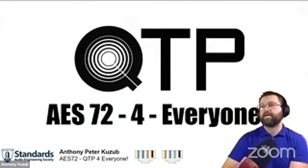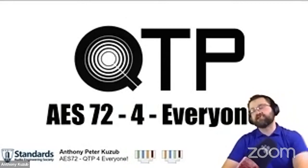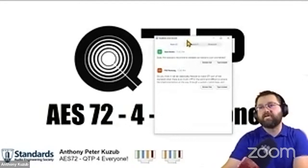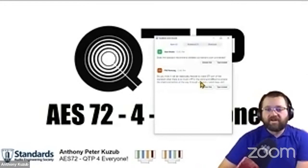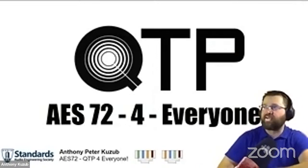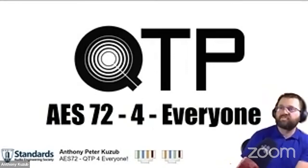Do you think it's realistically feasible to make STP part of the standard, or is there so much UTP in the world it's difficult to ensure the shield connection through the system, patch cords, et cetera? Okay, so no, I think there's just such a ubiquity of UTP, unshielded twisted pair, in the world. Again, it comes down to system engineering, and that can go a couple of different ways. Some people use the fourth pair just as the ground shield connection, and there were previous iterations of this type of connection that used a pair of them as shield connections. But again, it comes down to the quality of the transceiver.